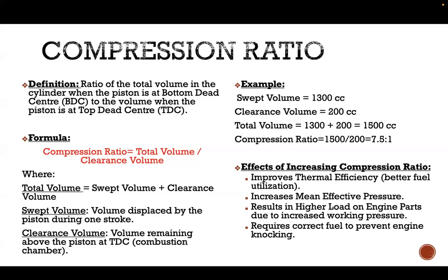This is going to be a problem, because by knowing your compression ratio, and to what extent you can compress, you have to choose the correct fuel. What grade of fuel can you use so that you don't have knocking? Knocking is pre-ignition. When compression is happening, we know that our pressure and our temperature are going to increase. If I compress it to a very great extent, it will increase all the way to a peak value where, even before we give a spark, it just starts combusting, which is going to be a problem for us.